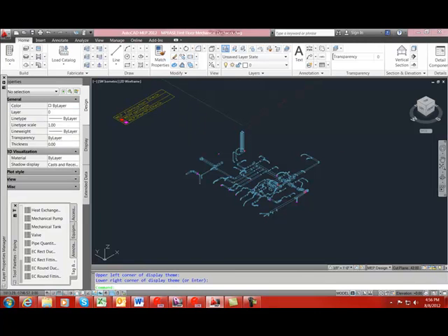Now this display theme will color all fittings red that came in without a default and specification assigned to it. The typical reason that these items would be colored red is that there was not enough space to create the fitting as specified in your manufacturer default.